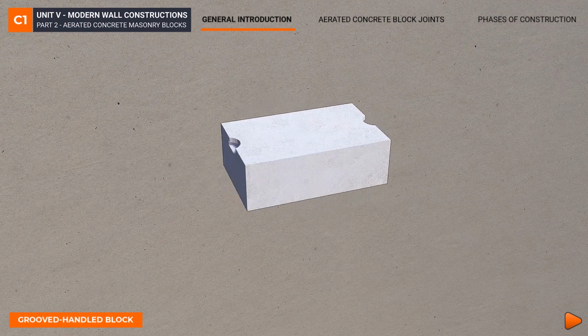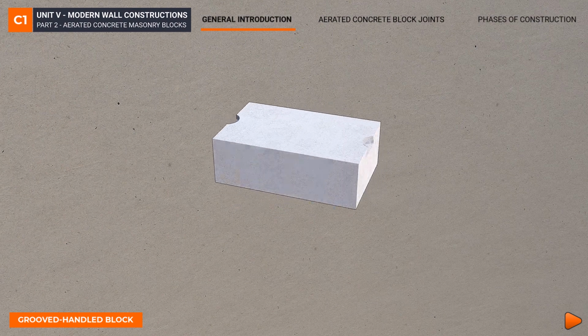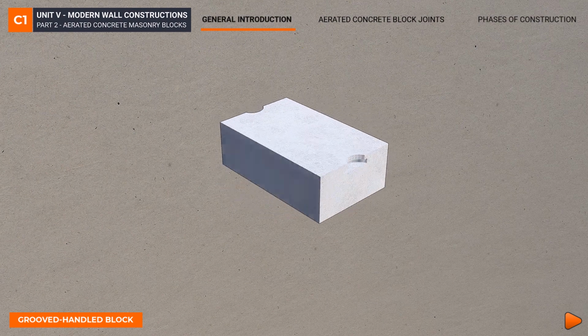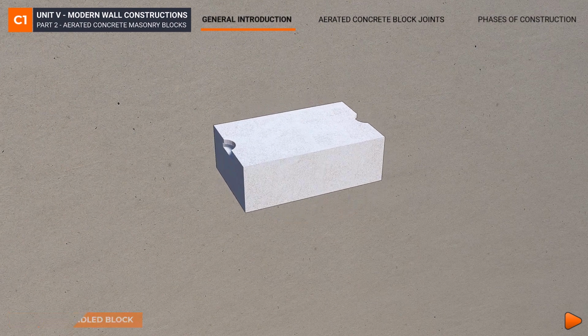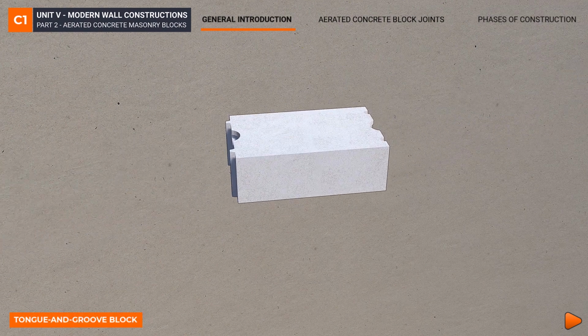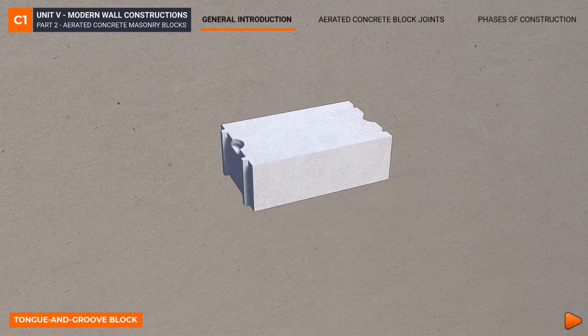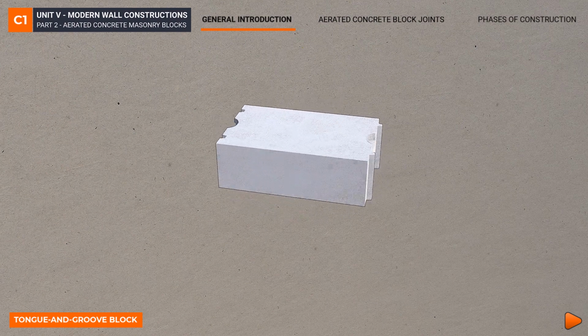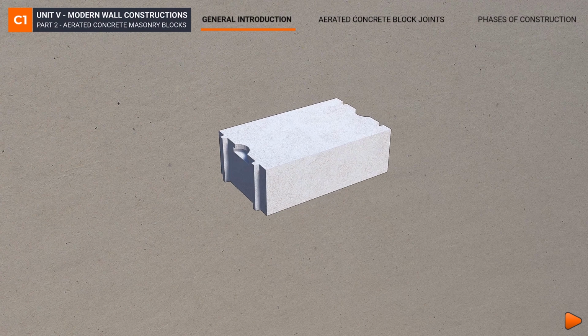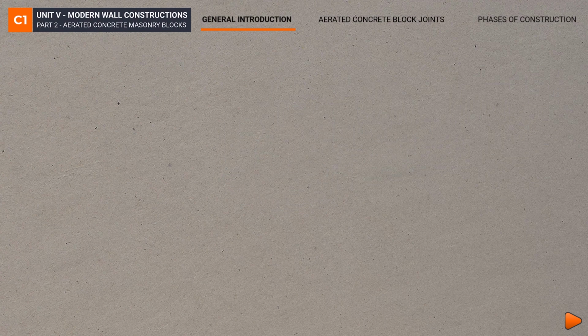The blocks are laid in a stretcher course only, with typical lengths of 50 or 60 centimeters and widths of 30, 37.5 and 50 centimeters, which determine the wall thickness. The average height of the blocks is 20 centimeters. The typical joint size is 1 centimeter, which gives a course height of 21 centimeters.